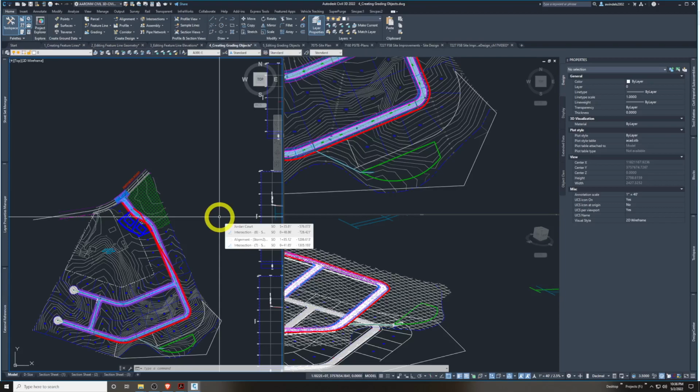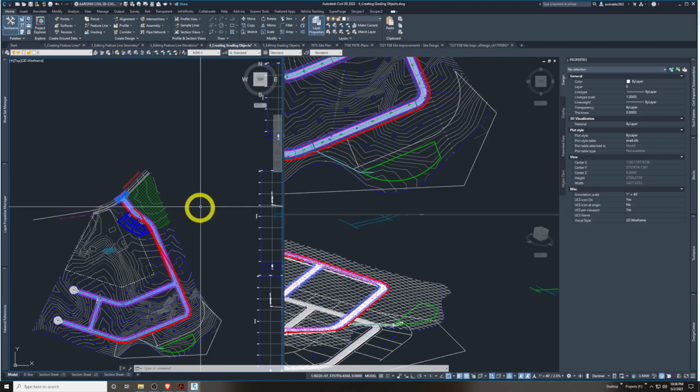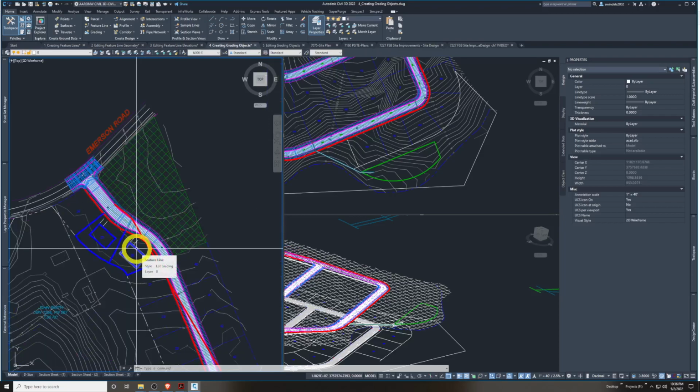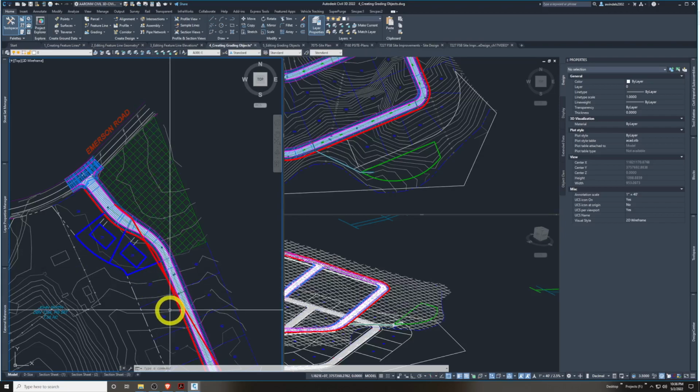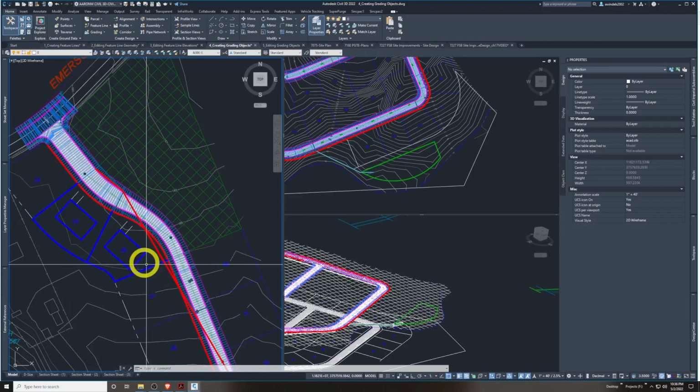For example, you might have a well-built feature line of a building pad, and you want to grade up or down to a certain amount, whether it's a relative elevation or down to a surface, and the grading object will do that based on a criteria and a certain amount of grade. It will grade off of your feature line as its baseline. Basically, it uses the feature line as a baseline to grade off of.